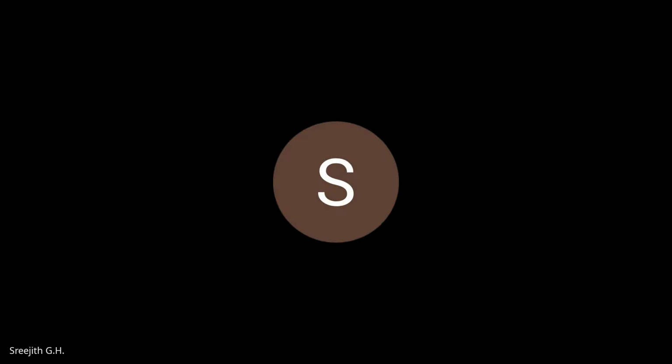Actually, the use of a seal coat may not be a very effective option in terms of stopping the propagation of cracks onto the bituminous layer. Its thickness is less than something like, what do you call it, I forgot the name. A chip seal kind of option, where you have a bituminous layer and aggregate spread on top of it.